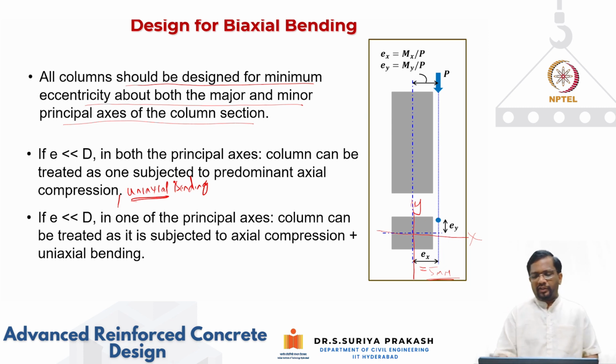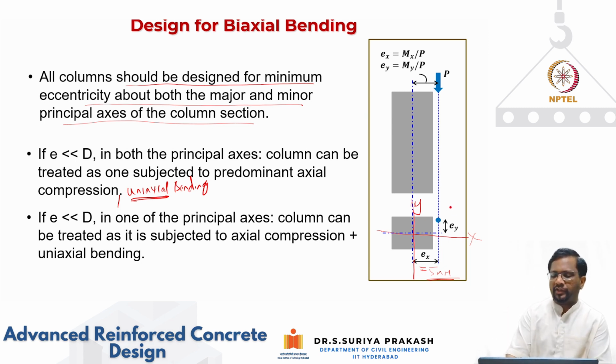Right. So in this case, let's say Ex is 5 mm and Ey is, let's say, 30 mm. So we know that now Ex is only 5 mm and that's not really going to create a major bending about the y-axis. So you will have moments only Mx, Pu and some nominal moment Mey that we need to account for in our design.